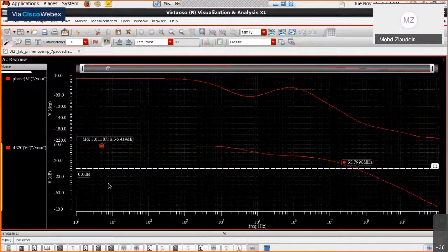Yeah, please. Sir, in this gm/ID technique, can we design for a specific gain? Here, the gain specifications were quite vague, like greater than 5 or something like that. Can we design it for a specific value? We can. It actually requires a large number of these characteristic curves to be generated first of all, and then maybe a couple of iterations.